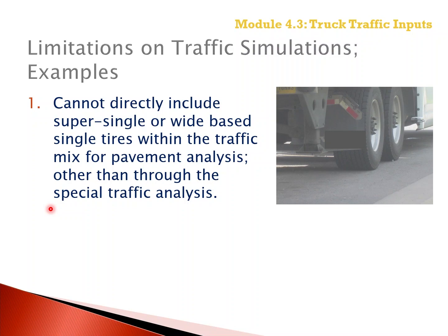So the first item is Pavement ME cannot directly include super singles. In other words, we don't have duals, we just have a single tire on each side of the axle, sometimes referred to as wide base single tires within the traffic stream.